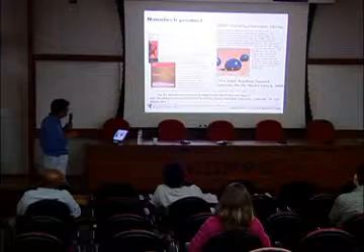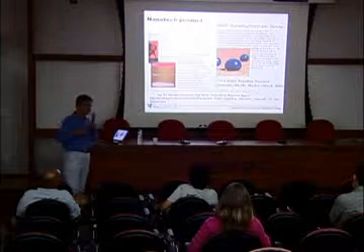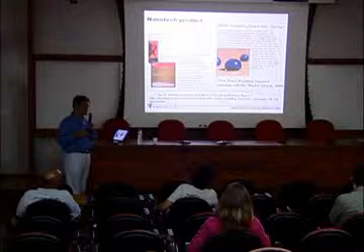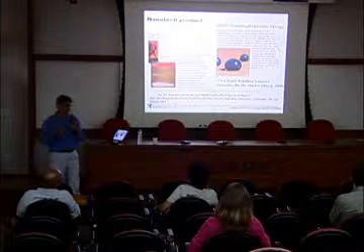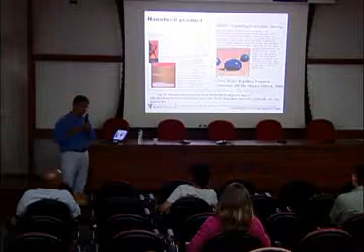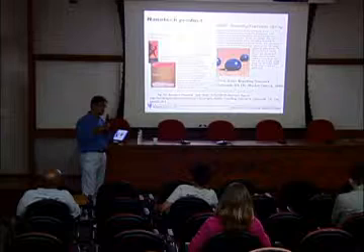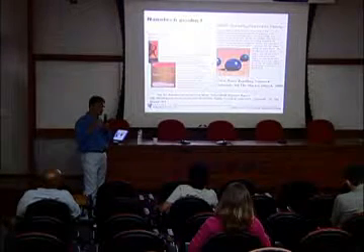But it's expensive. And if you see this surface, the contact angle is close to about 170 degrees. It's called hydrophobic. If you see the surface of Teflon on a frying pan, the contact angle is about 110, 120, 130. But if you use it frequently, the contact angle will become smaller.